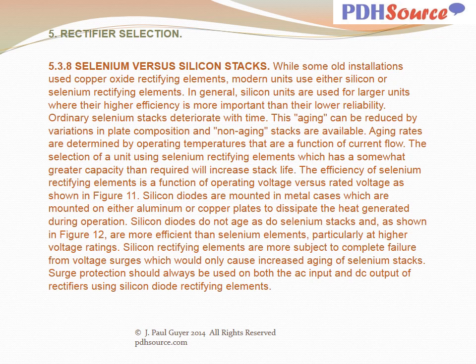Silicon diodes are mounted in metal cases which are mounted on either aluminum or copper plates to dissipate the heat generated during operation. Silicon diodes do not age as do selenium stacks, and as shown in Figure 12, are more efficient than selenium elements, particularly at high voltage ratings.